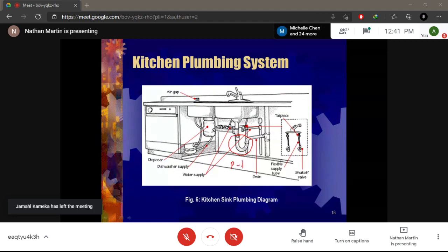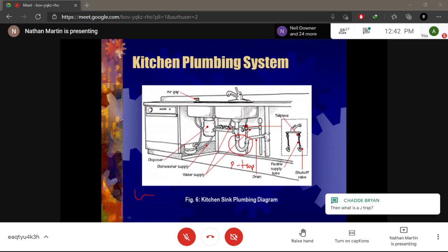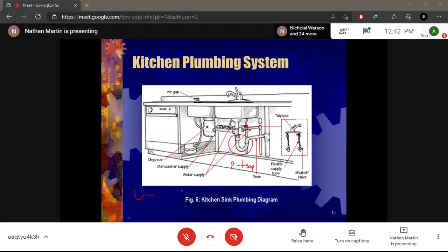Right? So it's a P trap. Now, why they call it a P trap is because if you were to spin this part, what will happen? Let me write it down here. So it's a P trap. And the trap is like this, right? But because of this joint here, if you were to actually, no, it's not a J trap, it's a P trap, right?